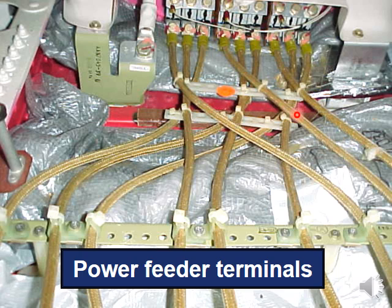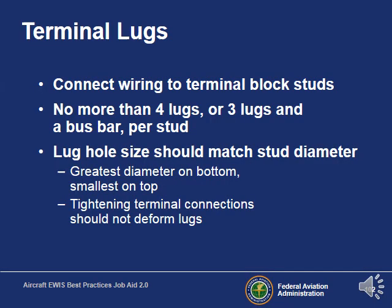Notice here, these power feeder terminals also are guarded against rotation and use the torque seal to indicate any rotation. They're also protected from each other with these bridges. There shouldn't be any contact here with the power feeder terminals. And notice they also are shielded, so there shouldn't be any corrosion here on the shield. Terminal lugs. It's important not to overload the studs. You can only have 4 lugs per stud, so make sure that you're not adding any extra terminal ends to each stud. And also, the stud's diameter and the terminal end diameter need to be pretty close together. You shouldn't have a really big terminal end with a very small stud. That will not transfer the electricity appropriately.